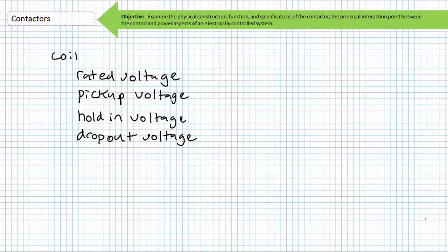A programmable logic controller with a 24-volt DC output cannot operate the coil of a contactor intended to operate on 120 volts AC. Either one must use a programmable logic controller capable of directly supplying 120 volt AC to directly operate the coil, or find a means of translating these two different voltage levels and flavors. Typically, such interaction occurs inside an interposing relay. It's basically a device that translates one magnitude of input to a different level of output. We'll discuss both programmable logic controllers and interposing relays in later lectures.